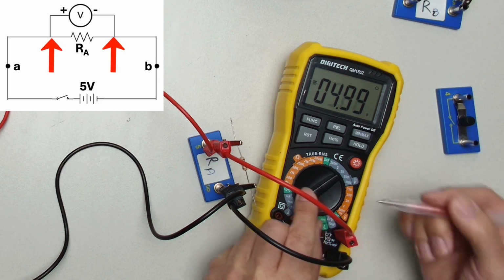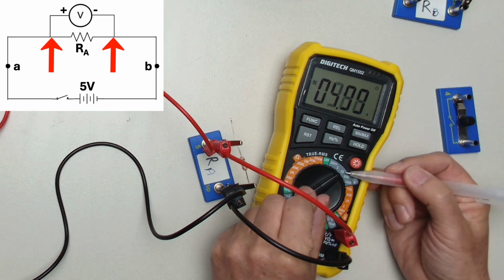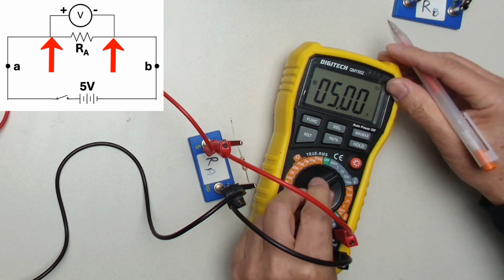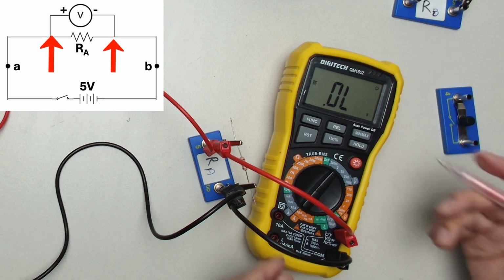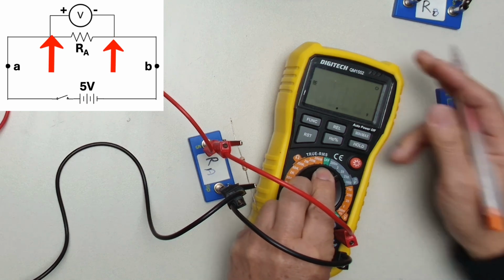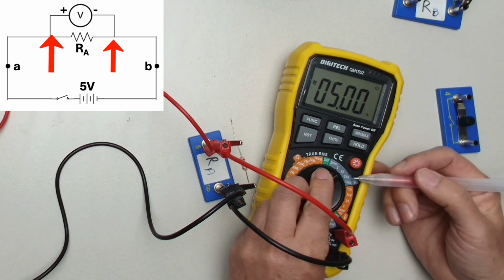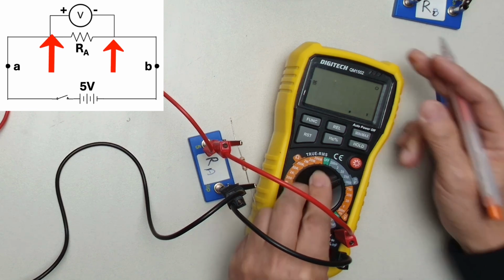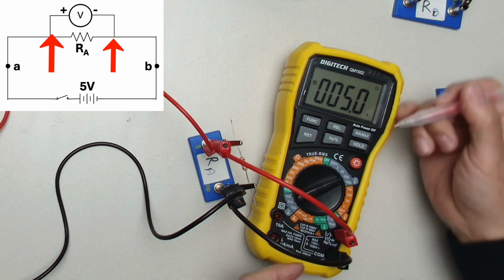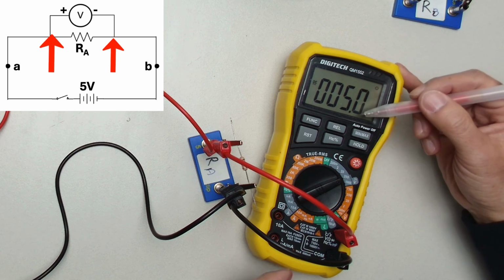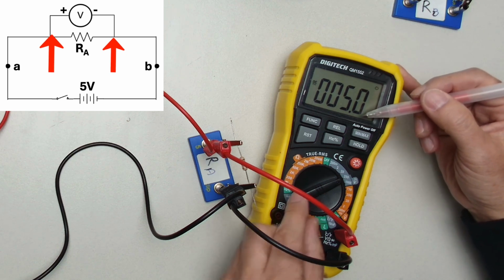And you will see if I turn the selector from 20 to 2, it's .OL, it means the range is not right. So we can turn it up. Okay, now how about if I turn it into 200 here? You will still get 5.0, but you lose information because you only get 1 decimal place displayed.